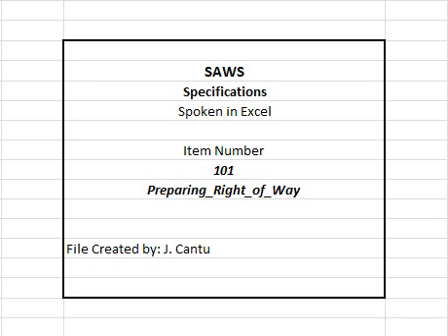2. This item shall also include the removal of trees, stumps, bushes, shrubs, brush, roots, vegetation, logs, rubbish, paved parking areas, miscellaneous stone, brick, drainage structures, manholes, inlets, abandoned railroad tracks, scrap iron and all debris, whether above or below ground, except live utility facilities. 3. This item shall not govern the demolition of buildings by the use of explosives. Such demolition work shall be governed by a special specification controlling the work.